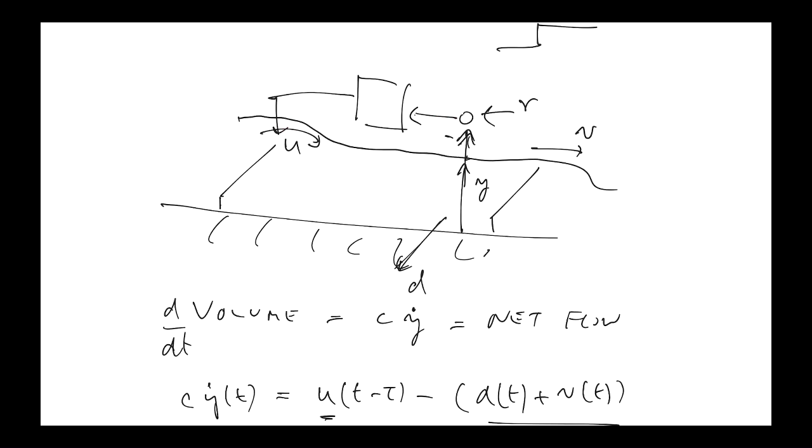And by adjusting the upstream flow rather than adjusting the downstream flow in order to regulate the water level, we end up with changes in the load propagating upstream towards the source, resulting in demand-driven release from the source.